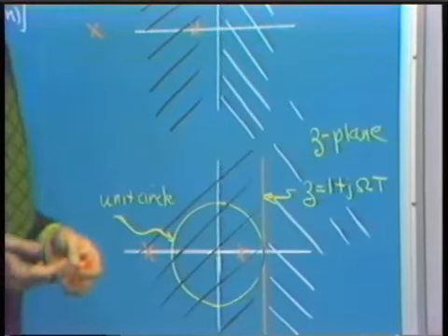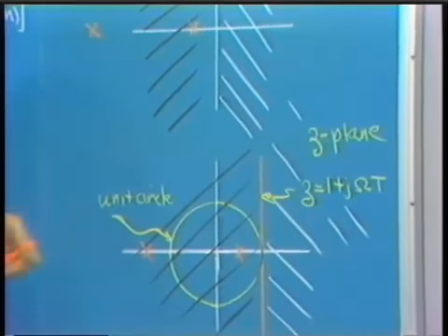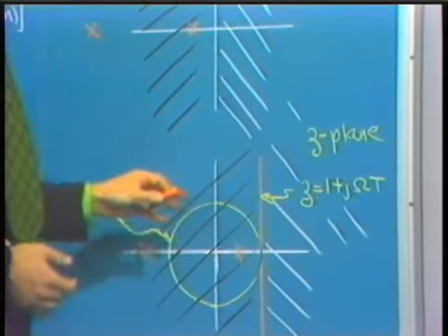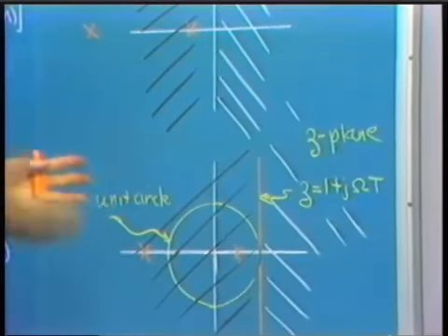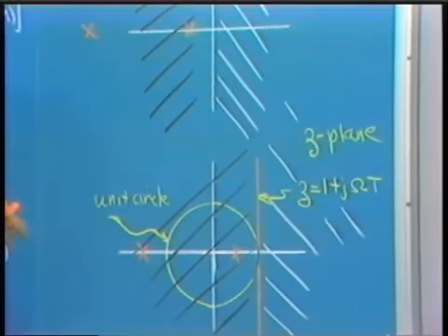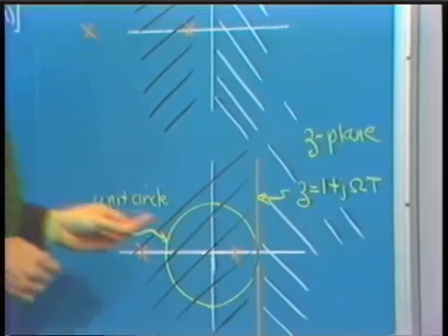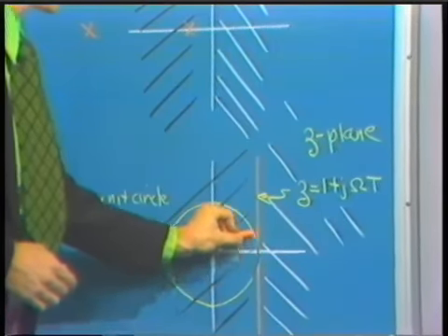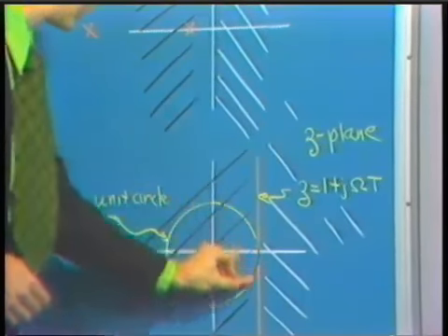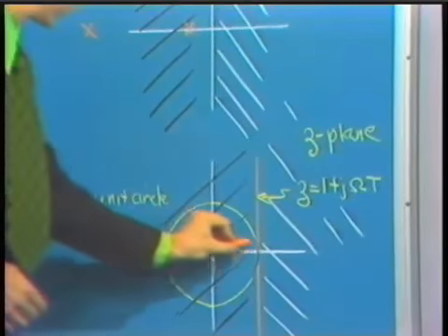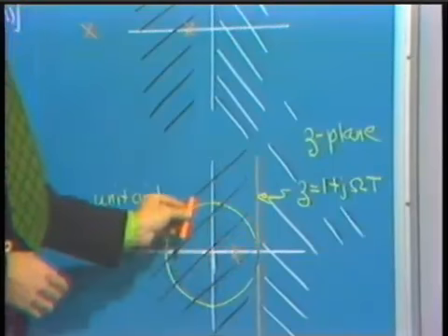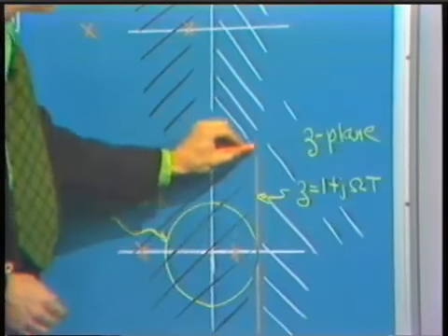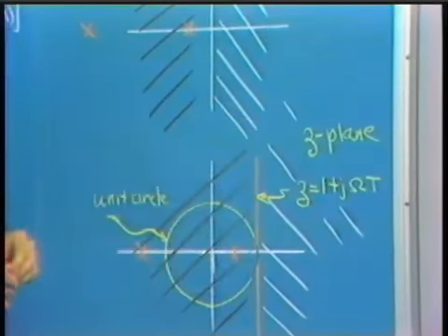And so consequently, if we oversample rather extensively, then we can in fact map more or less our analog filter to a digital filter. But in the more usual case, the digital signal spectrum occupies the entire unit circle, and clearly away from the region z equals 1, the unit circle deviates rather dramatically from this vertical line.